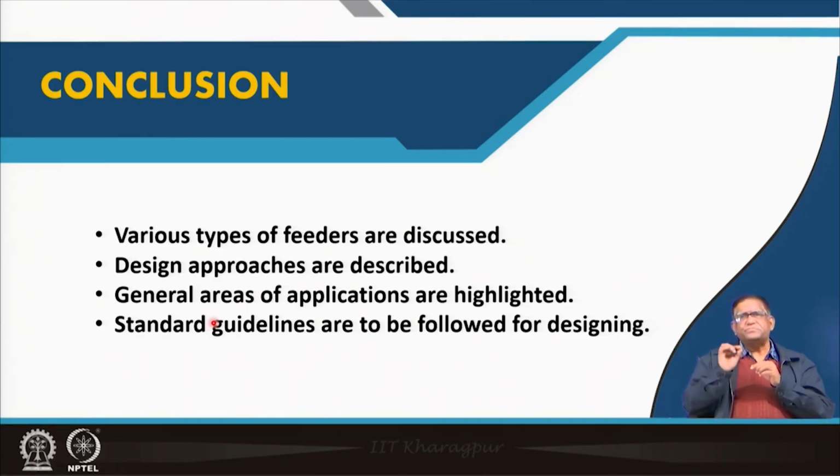But for designing and using, you must follow the manufacturer guideline. So, as a learning activity, please try to make a table of at least 5 different types of feeders, each of you, and write down their specifications. What is the driving power, what features are given, what type of material they handle, can they handle sticky material, powder material, bulk material, do they handle screened material, or will any type of material go, what type of temperature, can they take hot material or only cold material, can they be used only in indoor applications or otherwise.